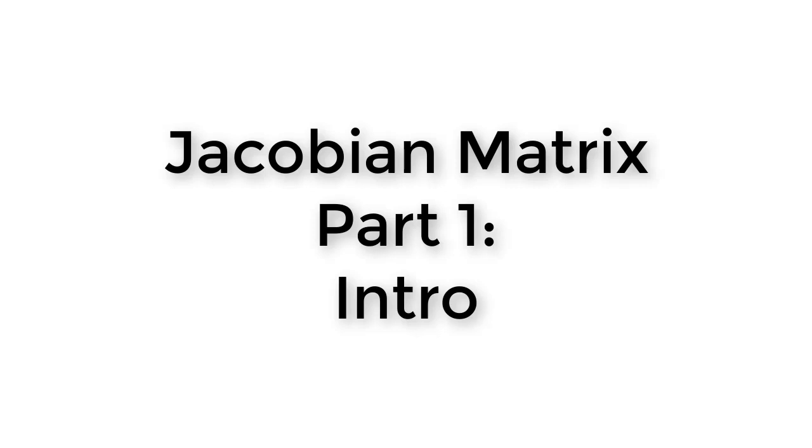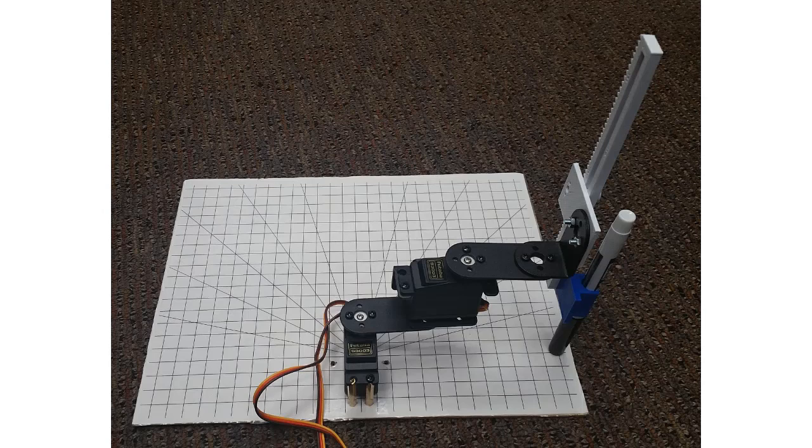Today, we're going to do the hands-on portion of the class first because it will help you understand why the Jacobian matrix is important, and it will set us up for writing the Jacobian matrix equations to control the velocity of the end effector in the next class on path planning. You should already have your SCARA manipulator built like this. Open PSoC Creator, and we're going to write some code to control the velocities of the servos.